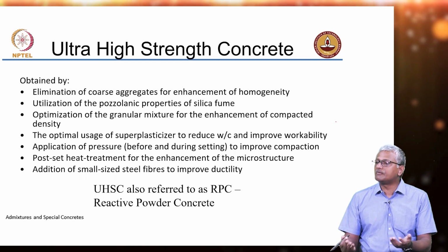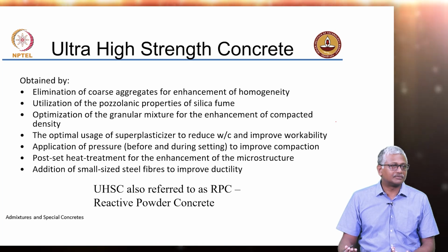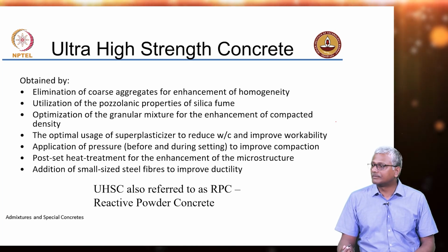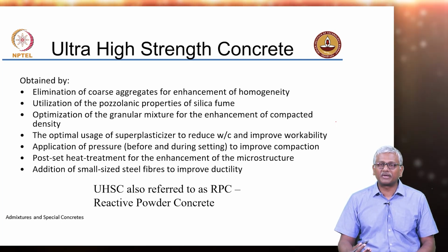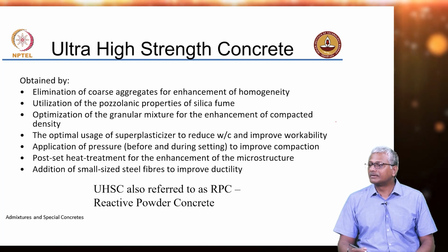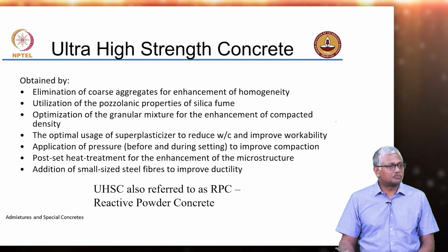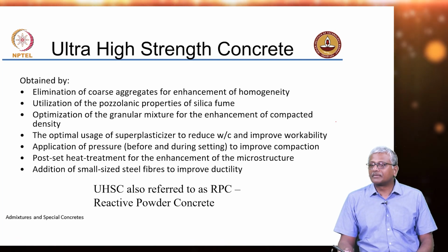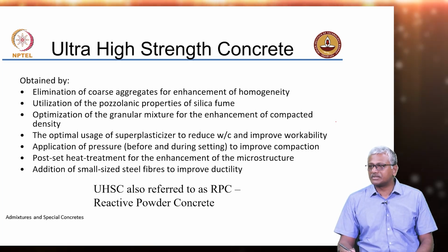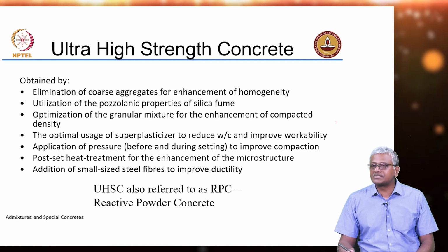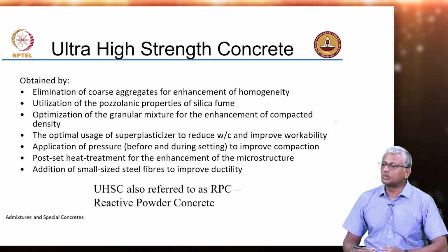Now in that case, why don't we simply use cement paste? We can't use cement paste because, well, before cost, there's a technical reason why we can't use cement paste. Cost is definitely a problem, but there is a technical reason. Strength you can achieve with cement paste, nothing wrong. That's why it's homogeneous, no? You can achieve strength. Dimensional stability, right? Without aggregate, you don't get dimensional stability in your concrete. So you have to use aggregate.